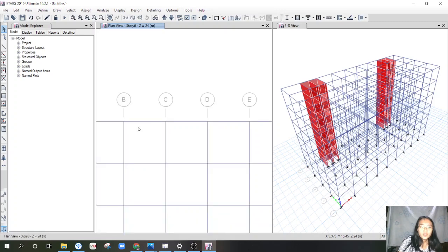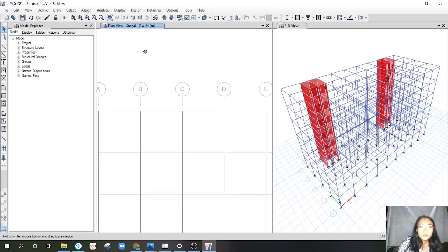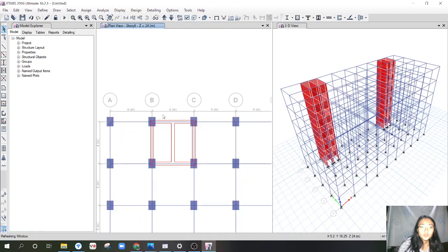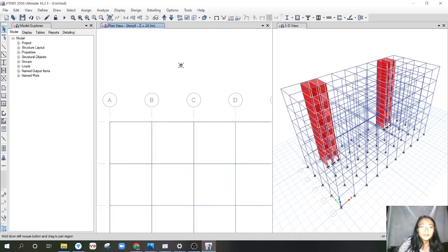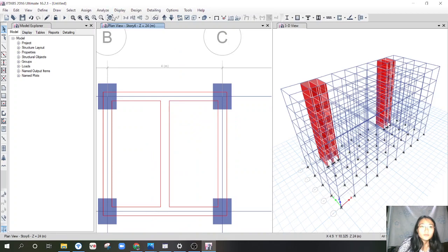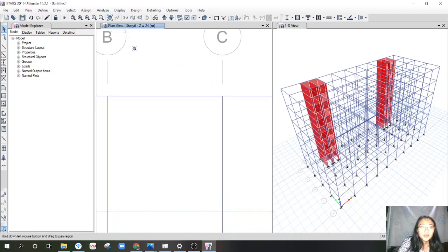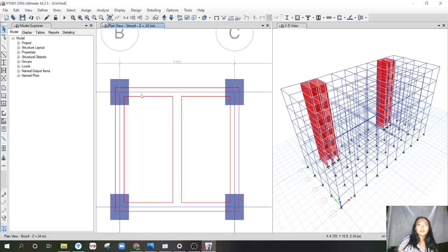So here, as you can see, there are solid lines. Since this will be poured solid, let's delete these unnecessary lines. Select the unnecessary lines to delete. In deleting unnecessary lines, you can just select the lines or the column and then quickly press the Delete key.